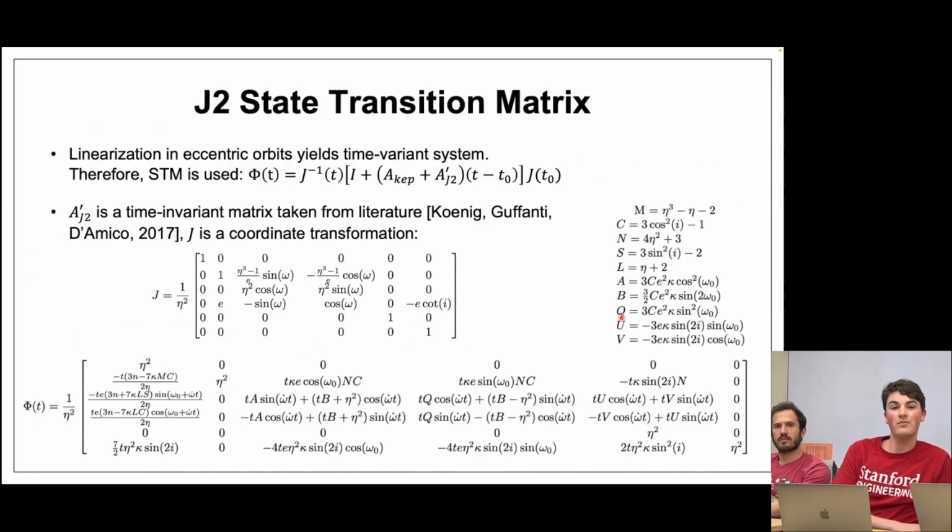When you map the relative position and relative velocity, you make an assumption of small separation. But when you propagate the ROEs in a linear model, you only neglect some of the effects in the orbital difference. So this mathematics is valid for much larger separation in general.